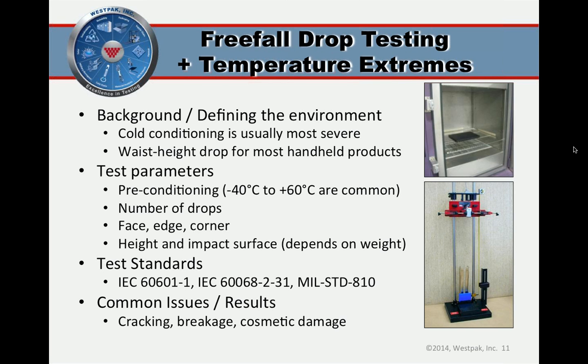Test standards here, the ones listed anyway, do discuss product drop, not so much temperature extremes. Those are often done, again, based upon the requirements of your product. Common issues and results are cracking, breakage, cosmetic damage, other things you would expect from product drop. Again, to reiterate, you may find unique failure modes with this that you wouldn't see with room temperature drop testing, and that's the reason why it is done.